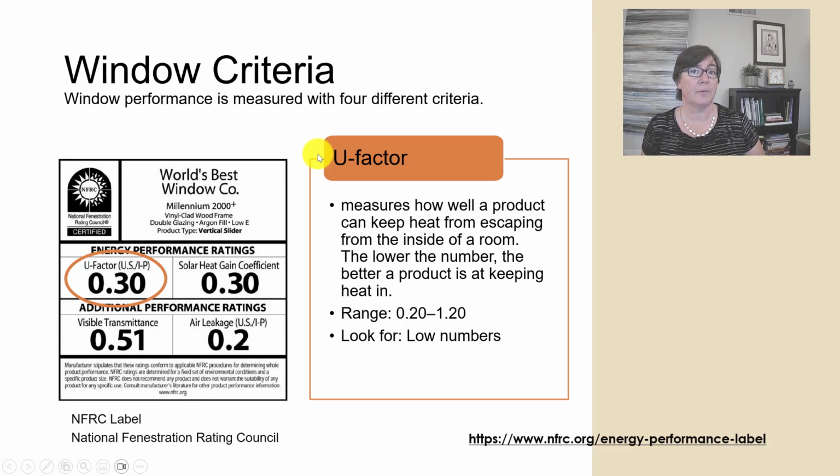U factor is going to measure the heat flow through this assembly, through this window product. The lower the better, and that range is roughly from 0.2 to 1.2. We've got a U factor right here of 0.3 on this particular window.